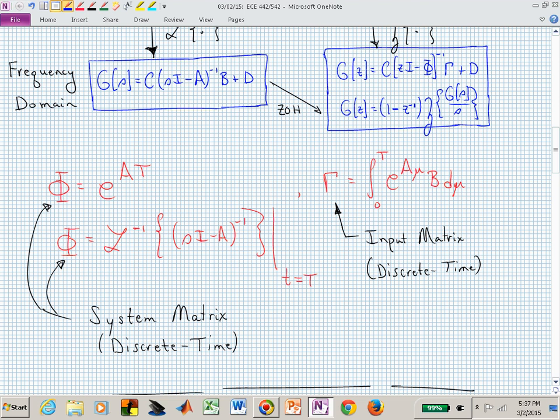If you're not going to close the loop, then you find your fastest mode and you sample 30 times that value in terms of determining capital T. If you are closing the loop, then you need to know how fast am I going to move this system or make it move in the closed loop, and base your capital T selection, your sample period selection, on that closed loop bandwidth that maybe somebody even tells you.